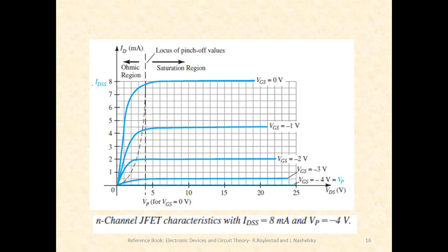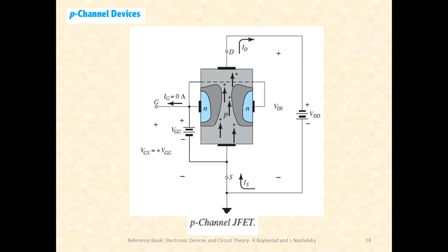So that's the entire graph of the output characteristics of a JFET. As VGS increases negatively, the pinch off occurs more quickly, so the resulting current will also be lesser, right? So we'll be getting lesser and lesser current. We have gone through these things in the previous class.